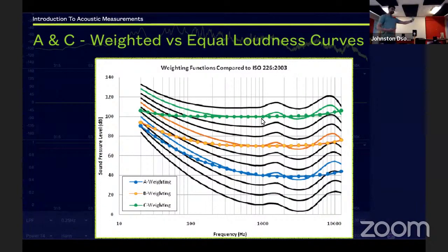Of course, in a live sound scenario, mostly system engineers will have an A weighted scale in front of them and a C weighted scale in front of them, and they'll reference both of them, because when you're playing music, it is not playing at one level, it is dynamic in nature. So to give them proper readings, they mostly will have two kinds of scales in front of them. For the louder parts, they'll look at the C weighted scale, to see how the system is, whether you're having even coverage from the front to the back, left to the right, top to down or not. Are you getting it?